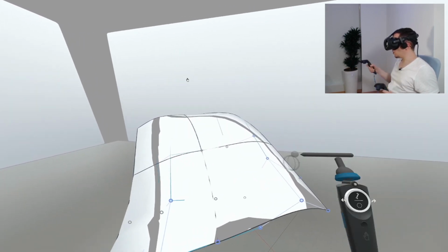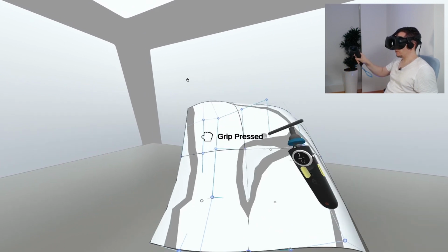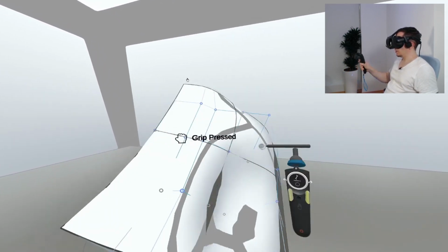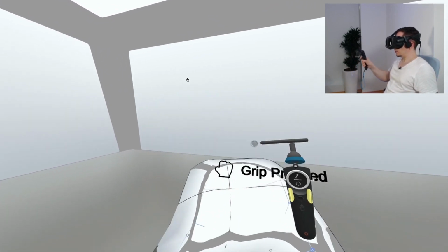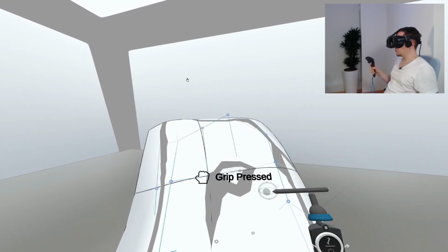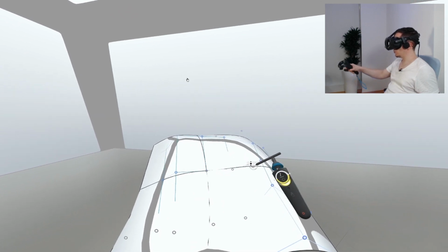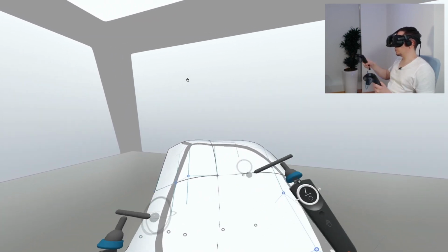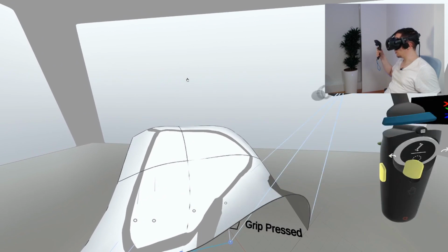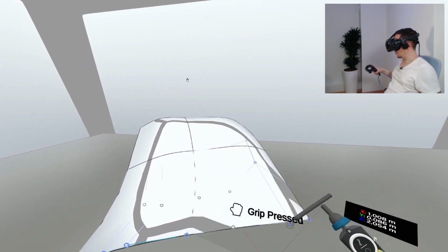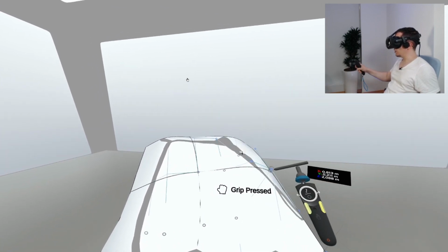You see that now I have made all these transitions G1 symmetrical. Everything looks quite smooth. So all joints are smooth and continuous now. And this is a very reliable way to enforce this requirement if you need it. You can always change it by toggling that mode again, but it's a very neat way to enforce continuity also through changes. So if you decide to change anything, this is fine, this won't impact anything else, but this will change the adjacent surfaces to maintain continuity requirements.